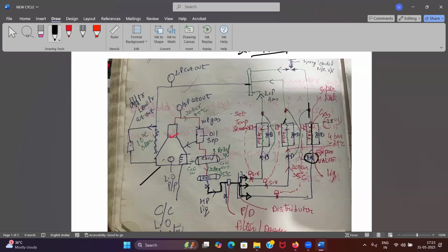Agreed? Okay, if it is creating back pressure and P2, I am having less amount of refrigerant and I'm preventing this refrigerant from flowing also. So that means my refrigerant temperature will be at a higher part, right? And if less refrigerant is going here, then maximum refrigerant will be going where? To these two lines, A and B, and that is what I want.